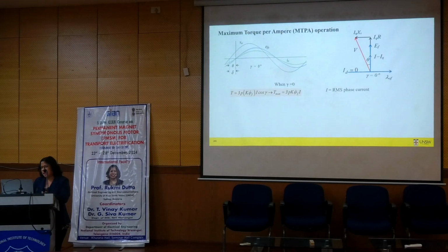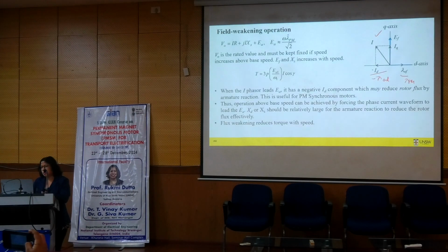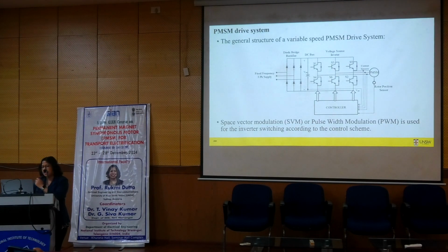Okay, so just before we move to field oriented control further, this is the structure you should remember that we will be talking about. In PMSM, we don't have this diode bridge rectifier, obviously. In a traction application, you will have the battery instead. You may have some kind of a boost converter as well, depending on your battery voltage and battery rating.